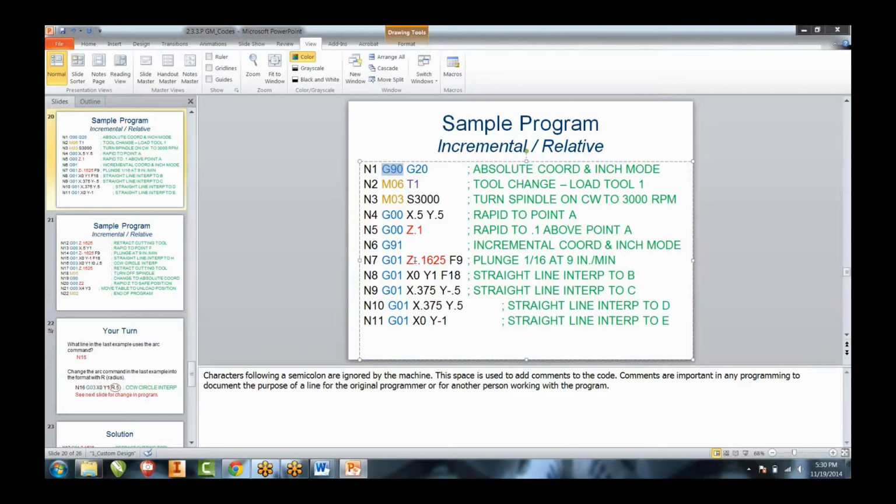Should add G28 for that. Yes, and some machines will understand that. Our IntelliTech machines will actually do G28s. That's one of the things we talk about, that for the most part we cut out a lot of extra codes. What he's talking about, the G28, is on your machine.